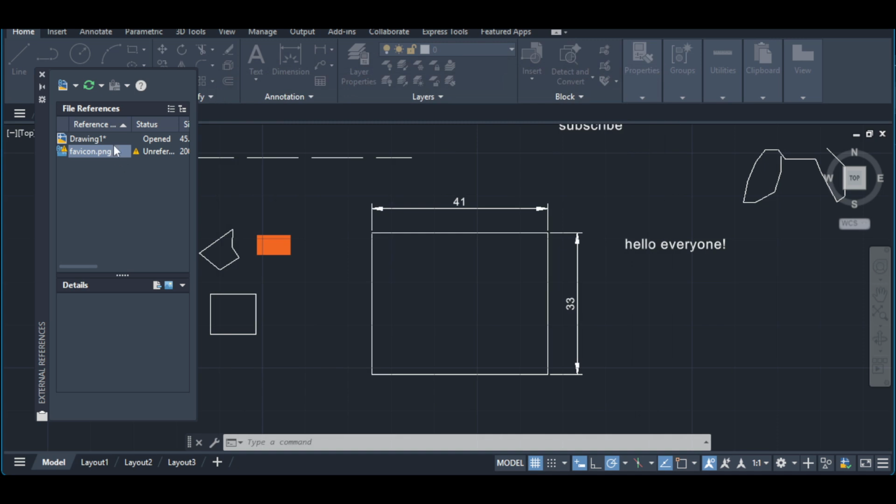A few helpful tips as you work. Keep your project files organized so paths remain valid, especially if you move folders or share projects. The External References palette is your hub for checking whether a reference is loaded, unloaded, or missing. If the source file changes, the palette helps you see that and refresh accordingly. Layers within an XREF remain controllable from your host drawing, so you can turn layers on or off to focus on what matters without editing the source. Finally, be mindful of naming conventions and consistent units across drawings to avoid scaling surprises.